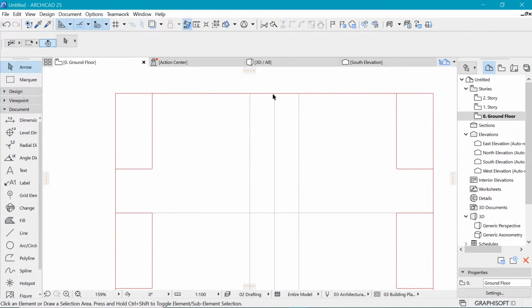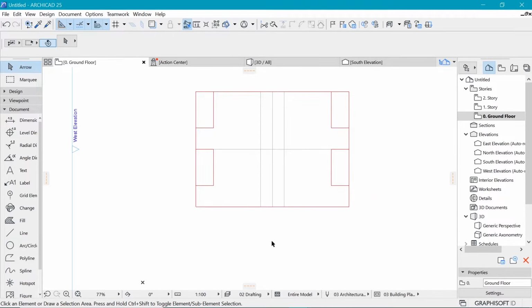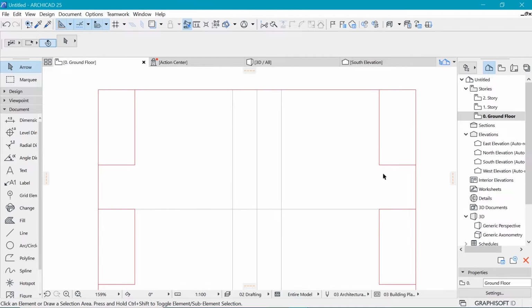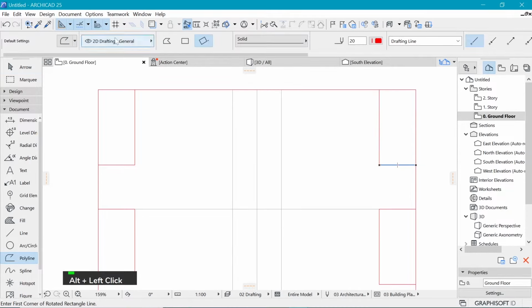Great. So let's create a space where the staircase is going to be, because people are going to enter from here and disperse to different rooms and take the stairs which are going to be here. So let's drag a copy. Let's pick up this parameter, which you can do by holding down Alt and clicking this line, or going to this icon here, which is the pickup parameter.